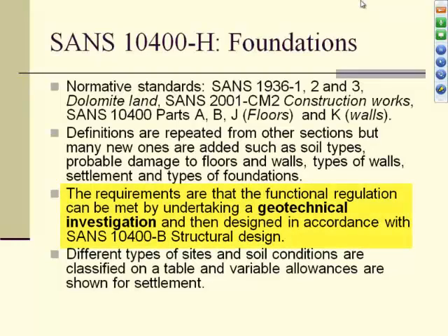Okay, so the functional regulation, this term comes up again. And this can be met by undertaking the geotechnical investigation and then having the design done in accordance with that structural design criteria. So the functional requirement says the foundations must be built to withstand the loads. They mustn't crack more than a certain recognized amount. They have to be able to withstand all the other criteria. Well, if there's a geotechnical investigation and the thing is designed by an engineer, no problem.